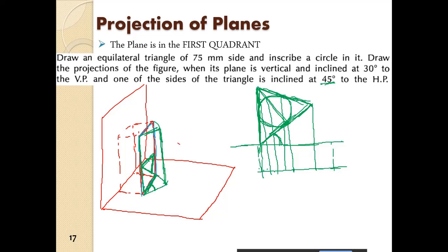All right, then now when we have obtained these various points from the front view of the plane when it was considered to be parallel to the vertical plane, once we have obtained that, now we will rotate the door. All right, so rotate the door. About this axis we will rotate it 30 degrees, all the points.